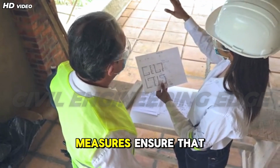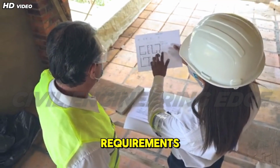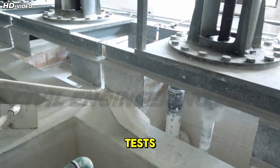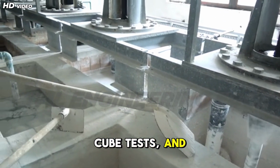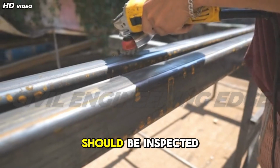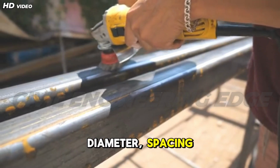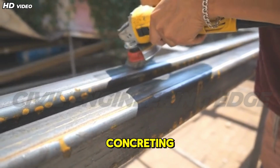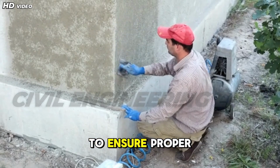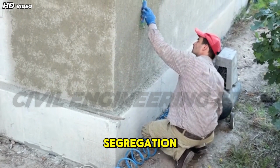Quality control measures ensure that materials and workmanship meet design requirements. Concrete quality must be verified through slump tests, cube tests, and proper curing practices. Reinforcement should be inspected for correct grade, diameter, spacing, and placement before concreting. Supervision during concreting is essential to ensure proper compaction using vibrators and to avoid segregation.